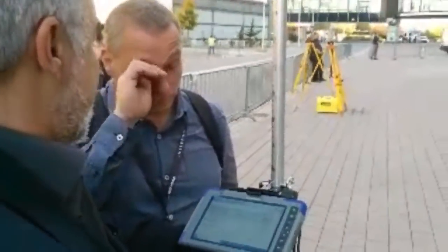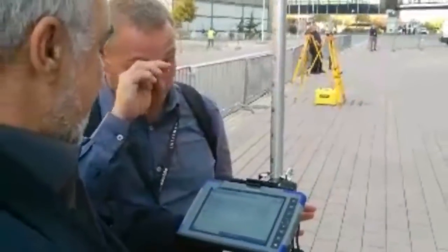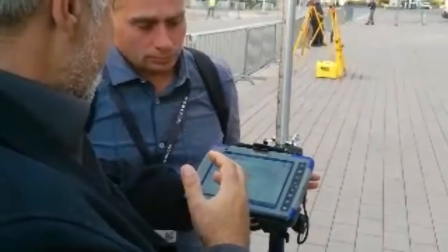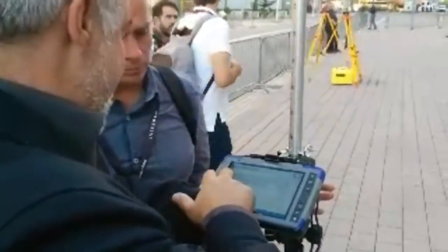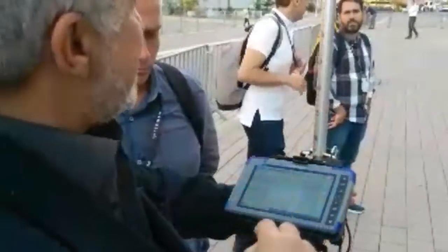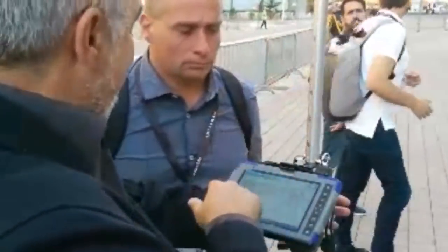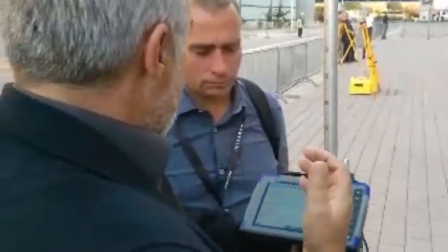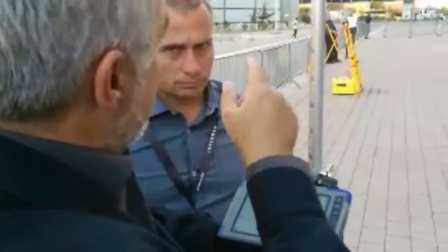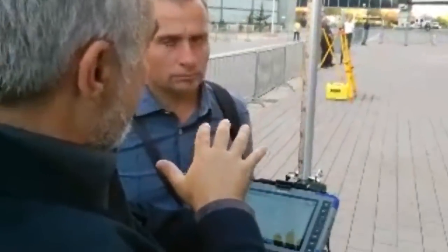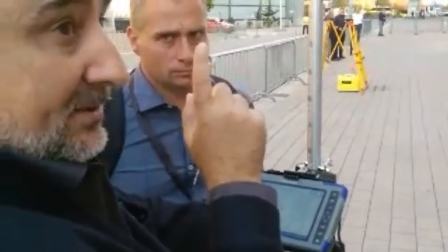How do we combine two different solutions and two different methods? Well, because they are different, in fact. I will do a resection. I could use localization, or I could do an auto localization. That could be another demo. I will do a hybrid resection right now. And because I'm doing a hybrid resection, I will use UTM, because it's my current setting for GPS. So my known points are UTM.